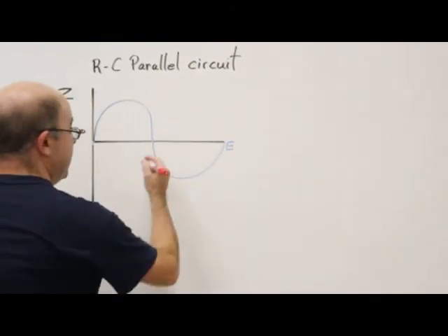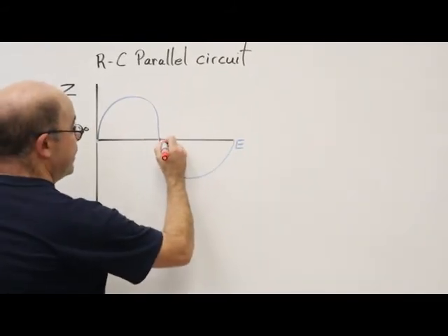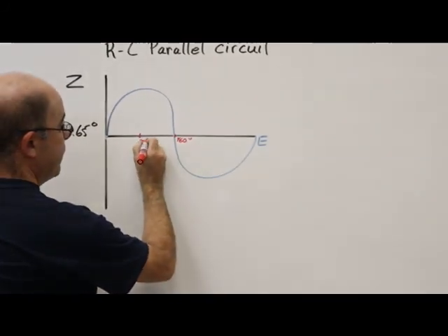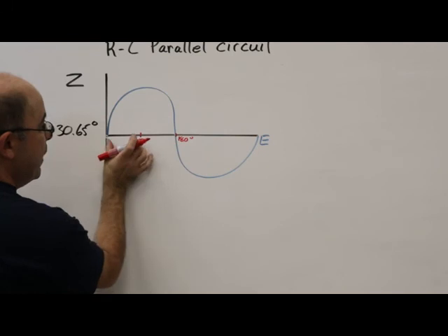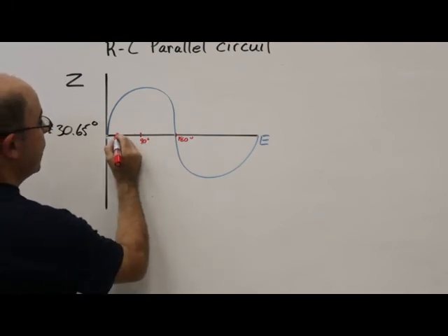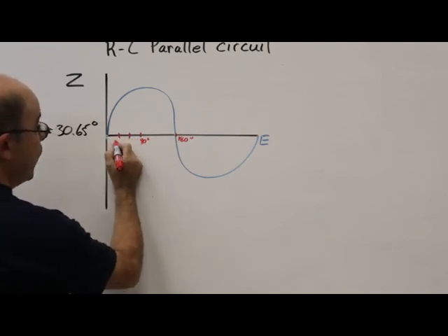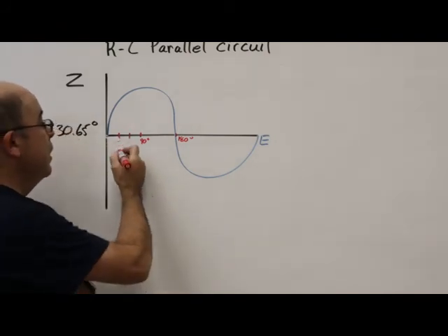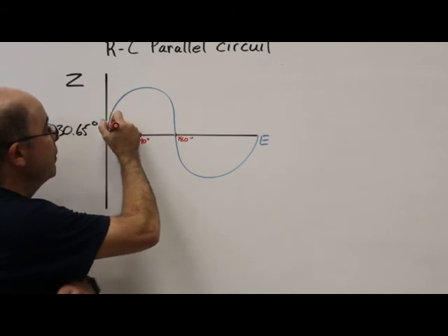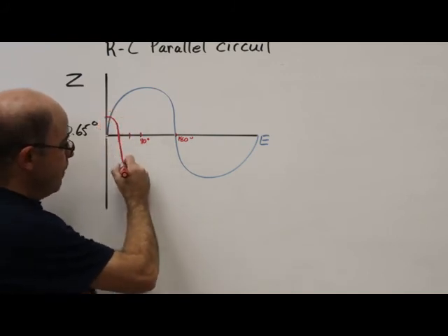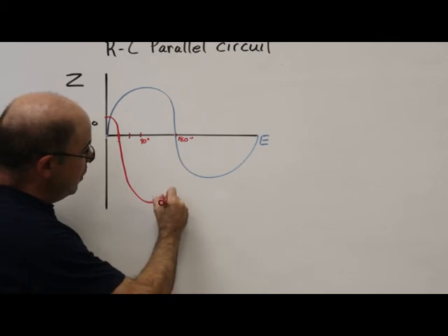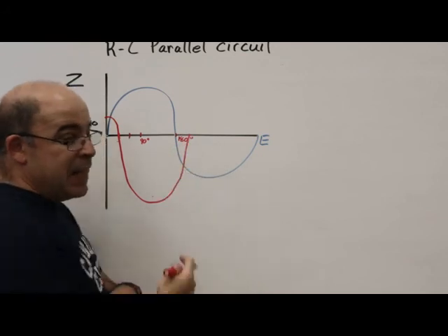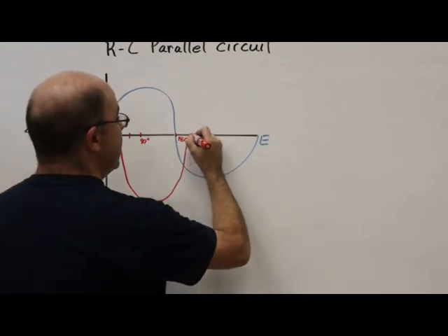So if this is 180 degrees, halfway represents 90, a quarter cycle. Well, if I was to break this up into 3 equal parts, right here, this would represent roughly 30 degrees. I'm going to start here, go into the negative alternation, and cross over at roughly the same distance to maintain that phase angle difference, and continue on.